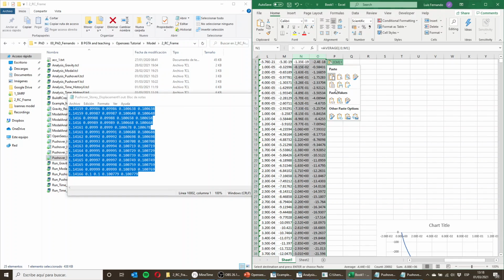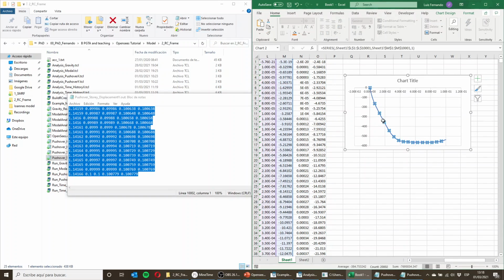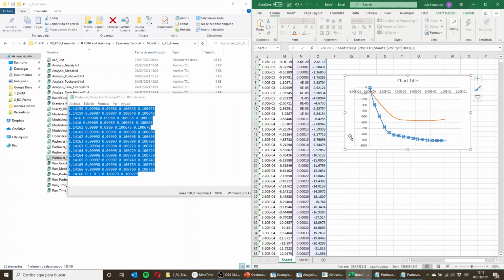And I'm going to do it also as values. There we go. So I'm going to drag this one here. I'm going to copy paste this curve. So my second curve that is overwritten, I will just move it over here. So we had 550 around, like the maximum. And now the second curve that we have is reaching 900 because this is in the strong direction of the columns, as you might remember. So obviously we get a larger capacity, even though we had a larger span as well. And then we can compare both directions of our concrete frame.